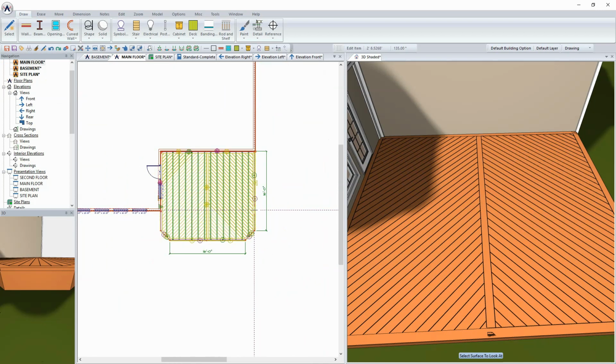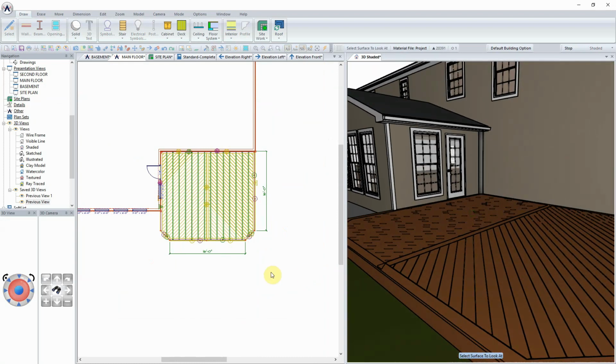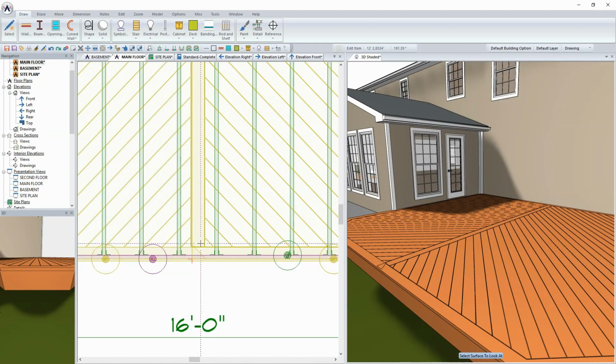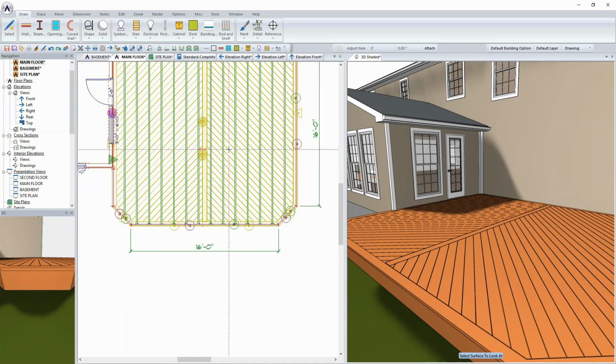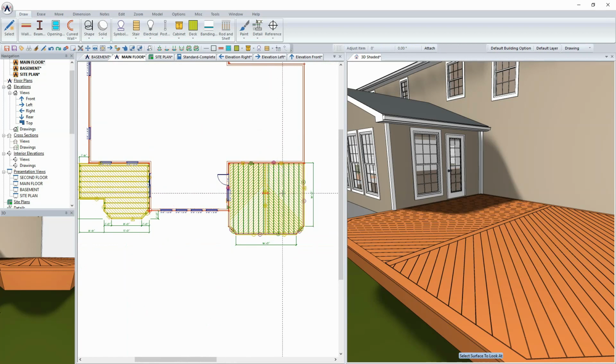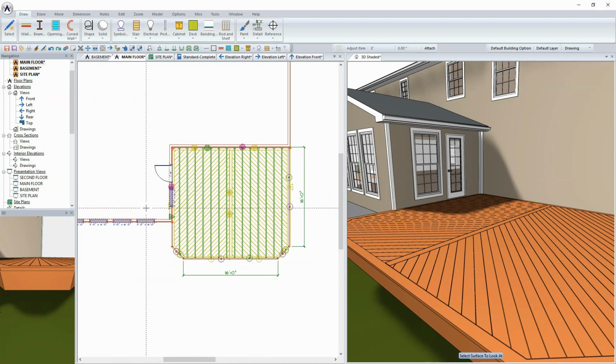And so now what we have is we have decking surface running in two different directions. We've got our parting boards in place, and even in the case of the parting board, we can actually adjust this if we wanted it to be at different directions or dimensions. So I can set it anywhere that I want. And so that gets our two decks laid out using this one tracing it in because everything was just easily conformed, and this one I got a little more custom in changing the deck surfaces, and so tracing the surface in as two different polygons.